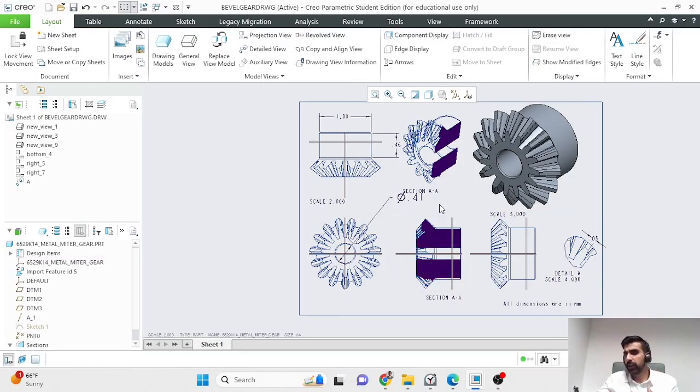This is more crowded than a typical engineering drawing would be, but after you've added the principal multi-views and preferably one pictorial view, feel free to add section views and detail views as long as they're adding value. If they're not, don't overcrowd your drawing.